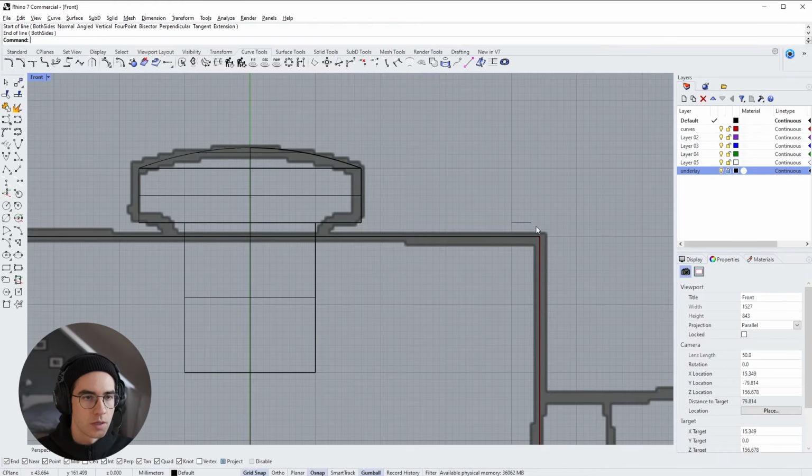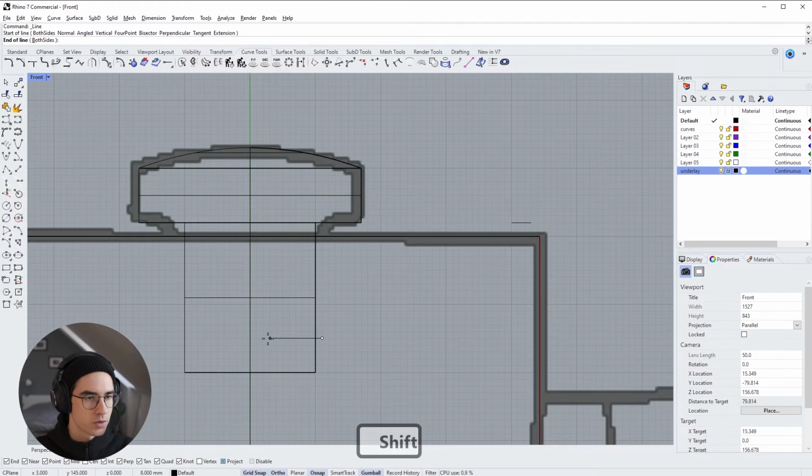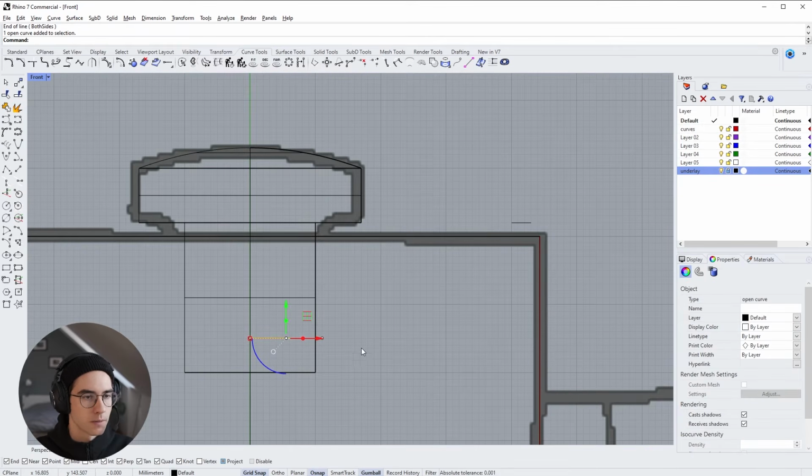So 3 millimeter line here, and then go somewhere you think it should start or end. I think it's maybe right about here. And I have grid snap on, so I know it's in a nice even distance from the top. And then hold shift. And what I'm doing is hit tab once in order to constrain again to the x-axis. And now my hand is free and I can choose any endpoint that I want the line to end. So here is a perfectly straight line.